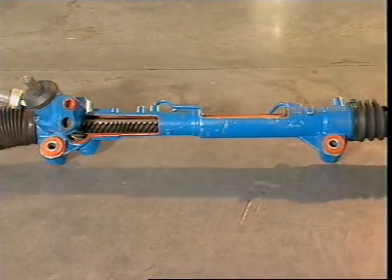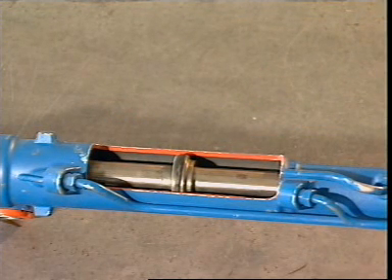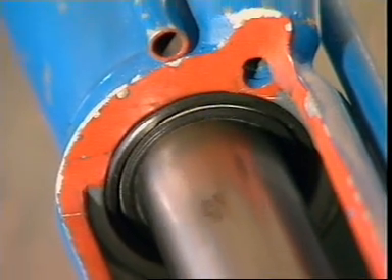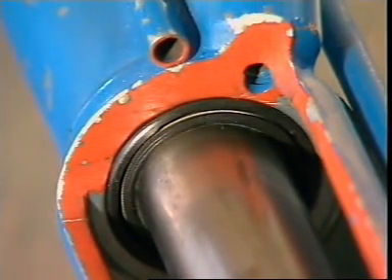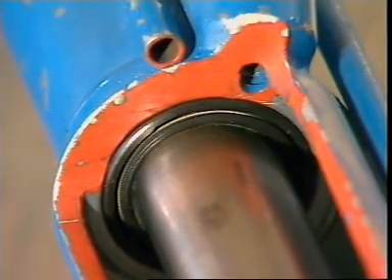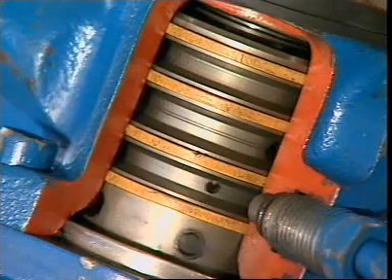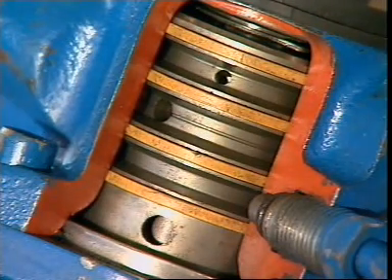In a rack and pinion steering gear, the piston is formed centrally on the steering rack, and the rack housing provides the working cylinder. Seals at each end of the cylinder isolate the power section from the rack and the helical pinion. Seals in the rotary valve section at the pinion input prevent fluid leakage there.